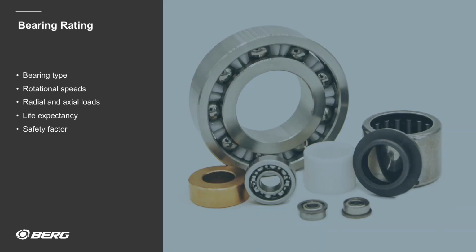Next is the selection of bearings. The type of gear you are using will often drive you to choose a particular bearing type. For example, helical gears produce thrust loads, and the selected bearing will often need to react this. Once the type is identified, the bearing is sized based on radial and axial loads, as well as the envelope available for it to fit into. If a rolling element bearing is too large, Berg also offers a number of bushings that are capable of thrust and radial loading to ensure that you can stay within the package size requirements. Berg has a handy reference in the back of the catalog for inner and outer ring tolerances based on ABEC rating of bearings to help you in the design process.